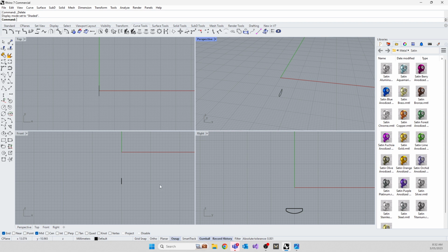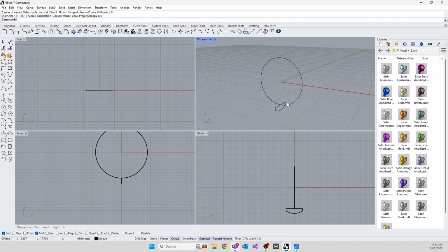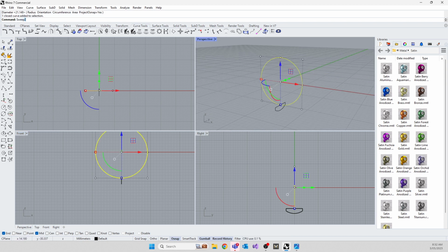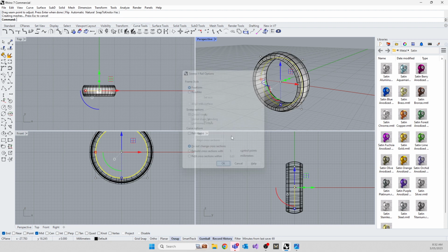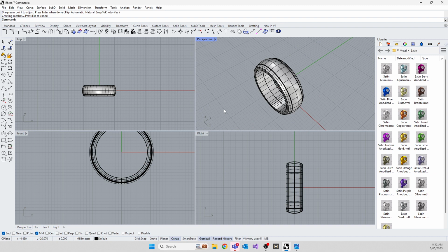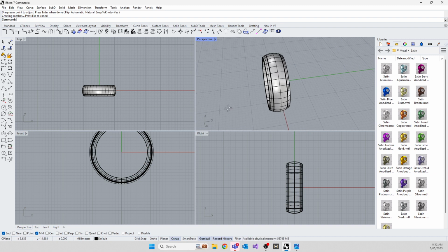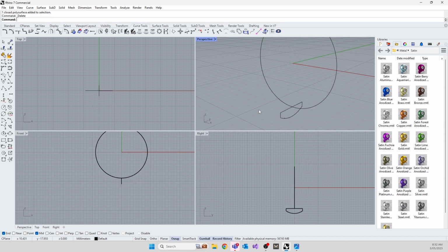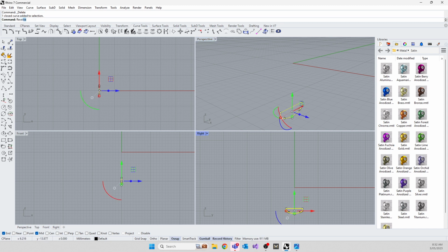So multiple ways. Let's draw a circle from 0 and let's bring it out to snap onto the mid of this ring there. So the one command in Rhino is sweep 1. You could grab the curve and you could run the word sweep 1 with that arc and go around, and guess what? Exactly the same result. There's many ways to draw something in Rhino. For me, the most efficient one for this would be revolve. I don't need the circle because I'm going to go exactly around the center of the world. So I'm going to grab that. The command is revolve.